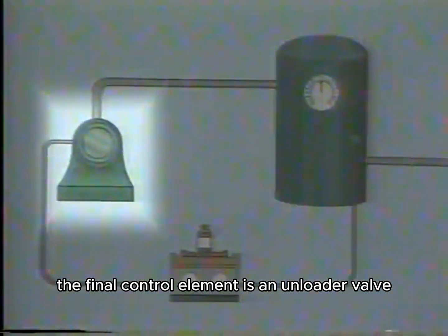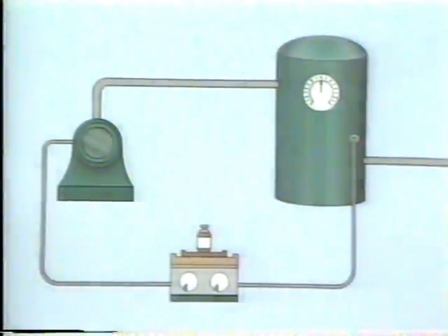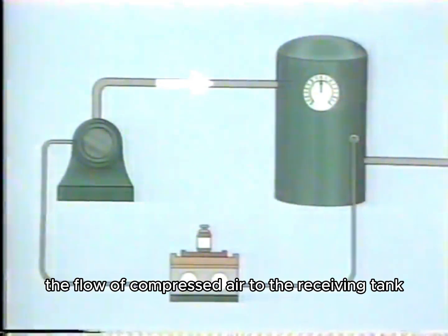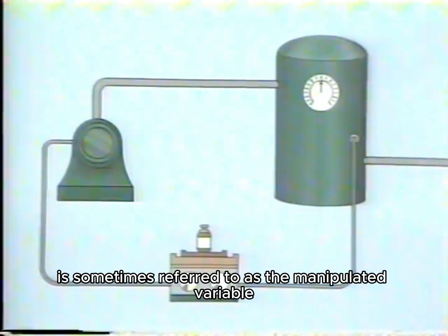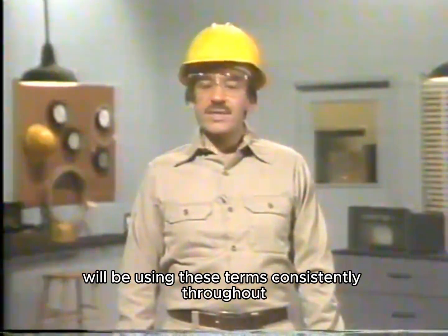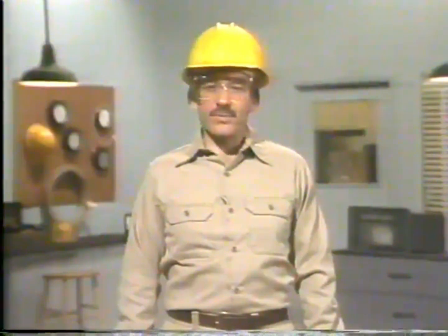The final control element is an unloader valve in the compressor. By opening and closing the unloader valve, we can manipulate the flow of compressed air to the receiving tank. The system variable that is manipulated is sometimes referred to as the manipulated variable. Controlled variable, monitored variable, and manipulated variable. We'll be using these terms consistently throughout the remainder of this program on basic control loops.